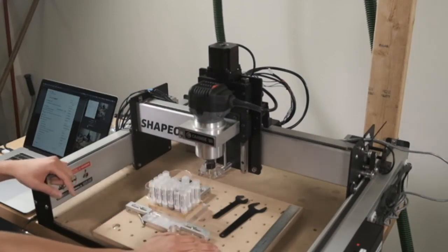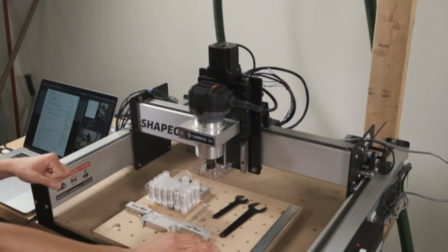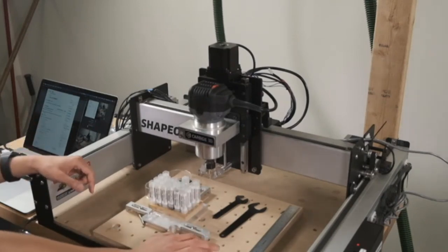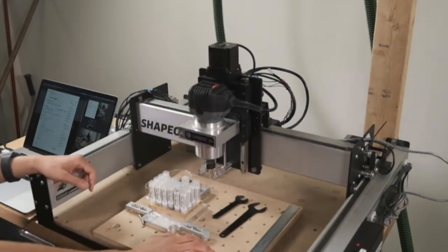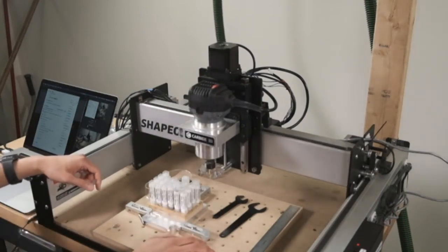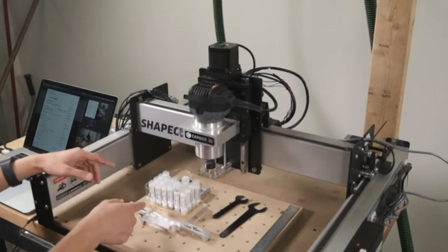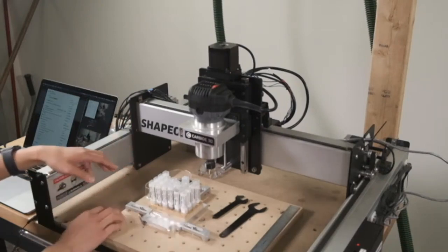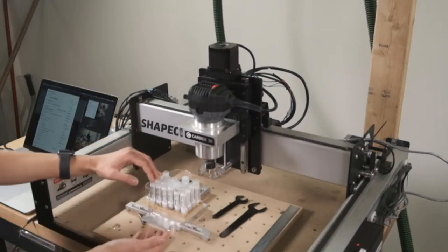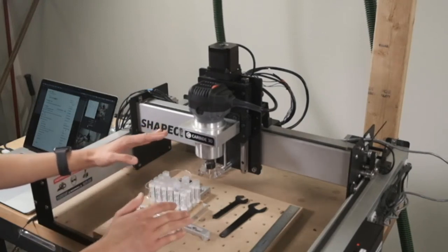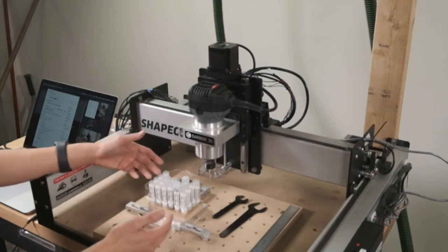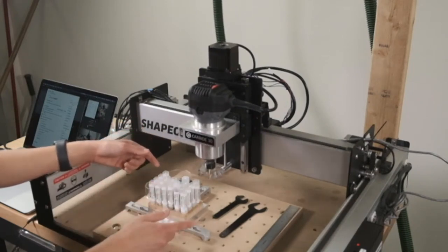I actually have a drawer at home filled with end mills I bought before I knew what I was doing, and they have never been used, and I don't know if they will ever be used. I have some high-speed steel end mills that are just really not as good as plain carbide for what I'm doing. So start with just a basic set of tools. Like if you're making a small sign, get some 1/8 inch, get some 1/4 inch end mills, get some V-bits, and then make your project. And then as your skills and your projects grow, then I would start adding tools to your inventory.